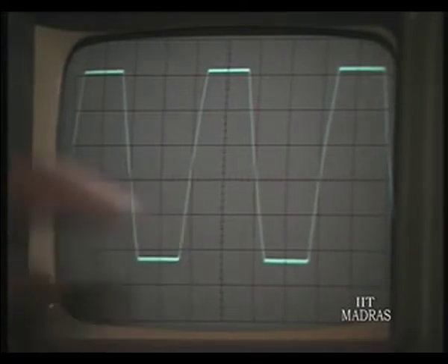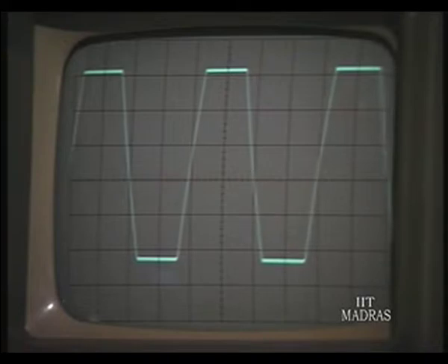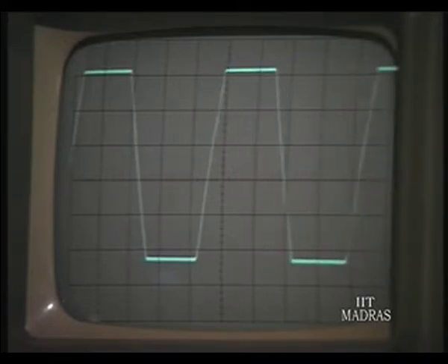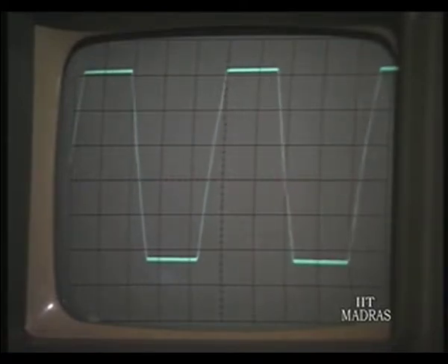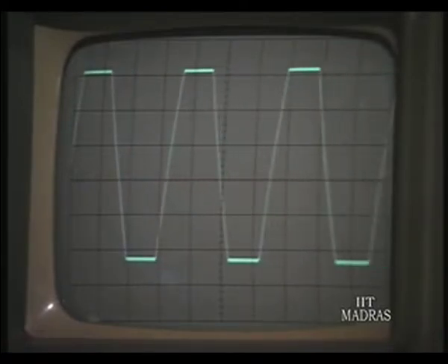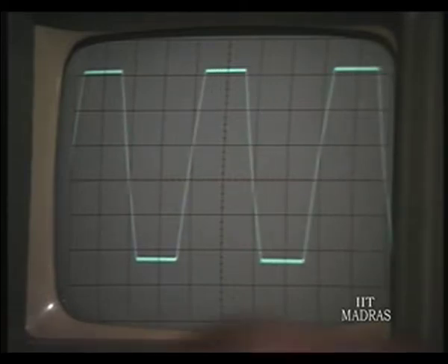About 4 kilohertz. And now you please show the input also. The free running frequency can be varied by varying the quiescent voltage. That is what she is doing. That is what is called tuning the phase lock loop.